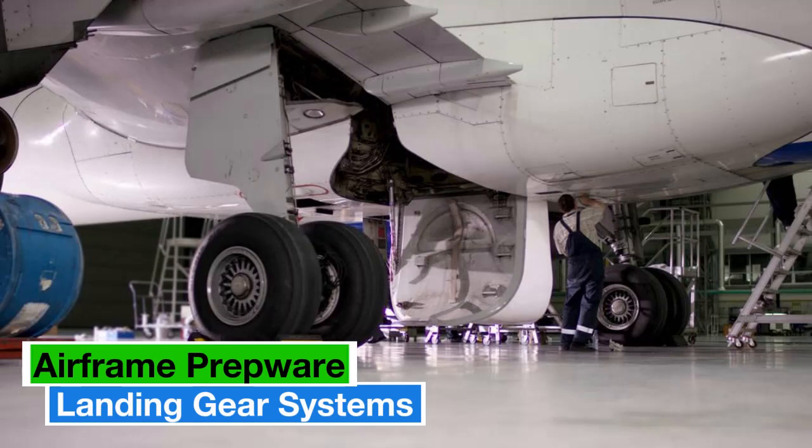When an airplane is slowed below approximately 20 miles per hour, the anti-skid system automatically deactivates to give the pilot full control of the brakes for maneuvering and parking. Number 2. An anti-skid system consists basically of 3 components: wheel speed sensors, control box, and control valves. Regarding the above statements, both number 1 and number 2 are true.